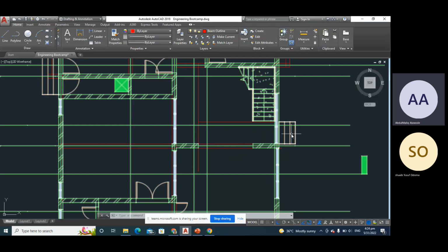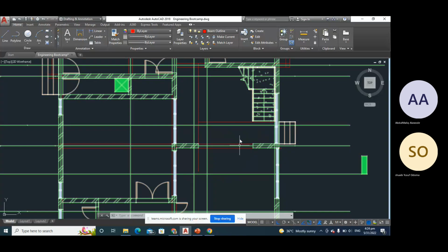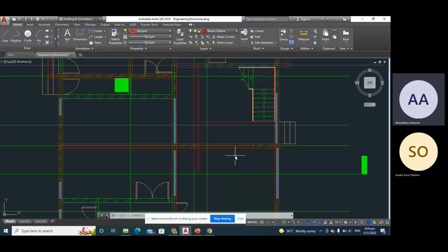So your bottom reinforcement for this slab, the first one that will be laid is going to be along the x axis, while the one they will lay later is going to be on the y axis. Now, if I'm taking it as cantilever, that means the main reinforcement for this slab is going to be the top reinforcement, and it's going to be along this part. Do you understand my point?